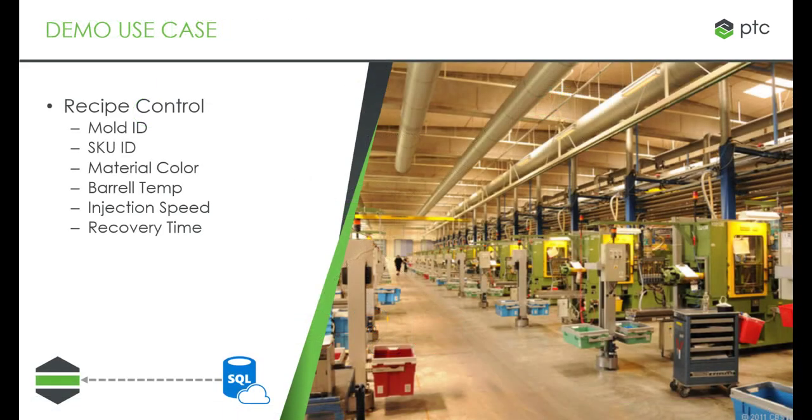The most common use case for the ODBC client driver is to assist in recipe management systems. In this hypothetical situation, we want Kepware to gather specific values for an injection molding application from a SQL database. These values include the mold ID, SKU ID, material color, barrel temperature, injection speed, and recovery time. We will showcase the 4 different access methods that the driver uses to retrieve the recipe data.